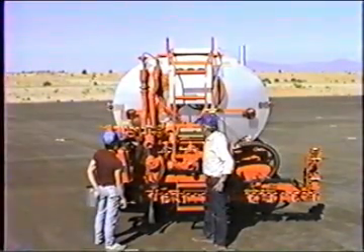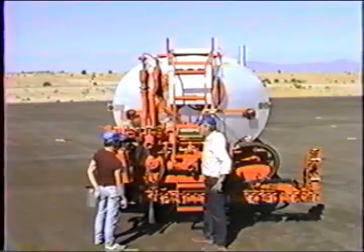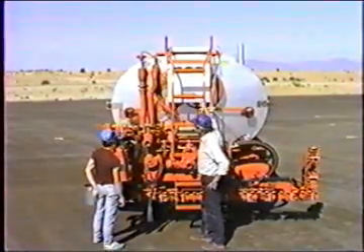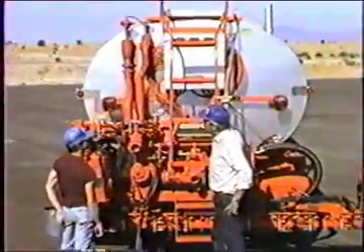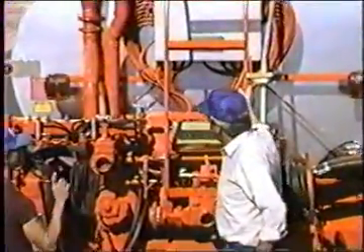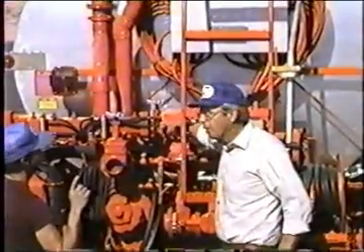Okay, the next pumping function that we'll do is to circulate the spray bar. We've heated the material in the tank up. Now it's time to circulate the spray bar and get ready to go to work. First thing we'll do is to open the spray bar valve.